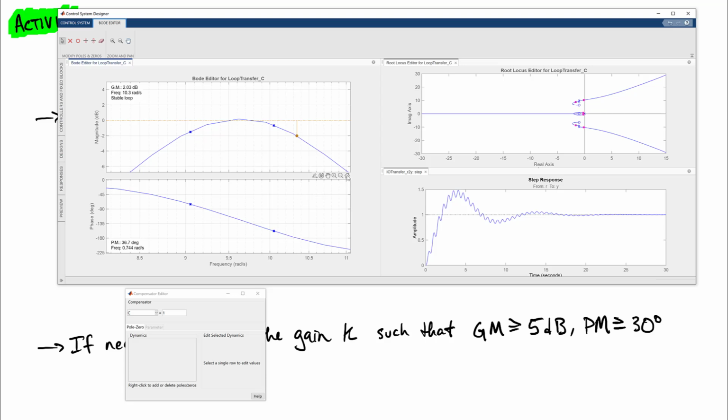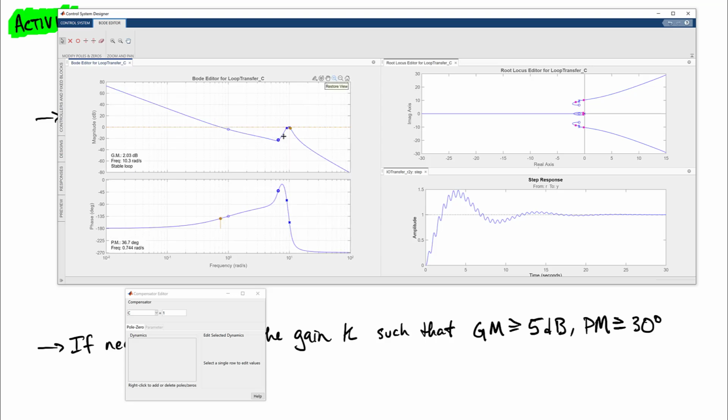And so just like when we saw it in the previous example, we wanted to find places where when we quantified either the gain margin or the phase margin, if there are multiple options for those, this again is which one is closer, because we're worried about which one is essentially making it so that any small perturbation or change in the gain may end up making the system unstable.